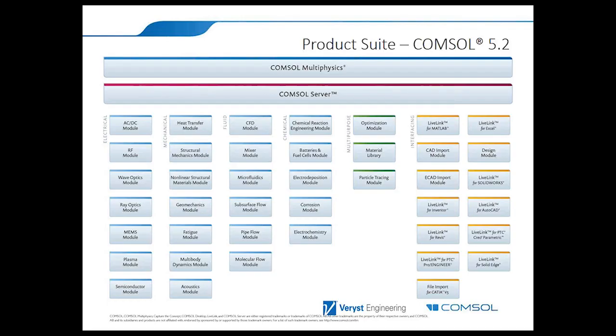Okay, so for our next question, let's see. Can COMSOL simulate the deformation of an artificial heart valve? Yes, it certainly can. It's an FSI problem. The difficulty in that kind of problem, in my opinion, is that when the valve is closed, that blocks the flow. So it's not easy to have a flow volume that contracts to zero, but it's doable. There are ways to handle that in COMSOL, so it's pretty well suited for this type of problem.